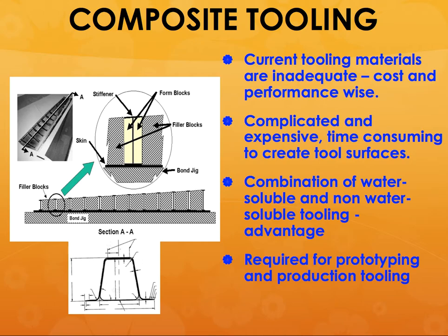So there is a tremendous difference between the shrinkage and expansion of the two materials. First of all, you have to account for the expansion of your tooling in your part dimensions. Second, that difference in shrinkage and expansion can cause the introduction of residual stresses into your part.